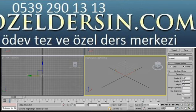We're going to use a cone primitive for this video. We'll go to the Create panel, Geometry, and select Cone. Let's drag out a cone here in the perspective viewport. Just drag it out any size. We'll come over to the Modify next, and we'll set our radiuses there.